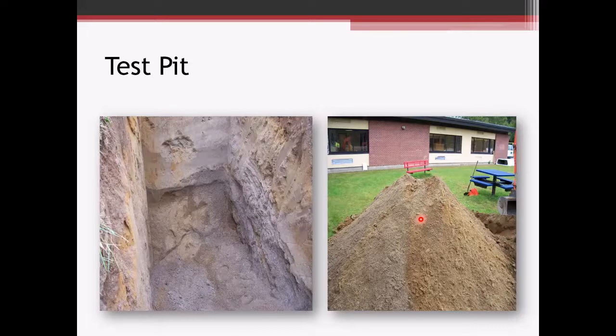The other good thing about test pits, as I mentioned, is we can get an idea of what the groundwater conditions are. If there's just a perched layer, what the seepage rates are, if there's going to be any special dewatering methods required if groundwater is encountered during a foundation excavation.